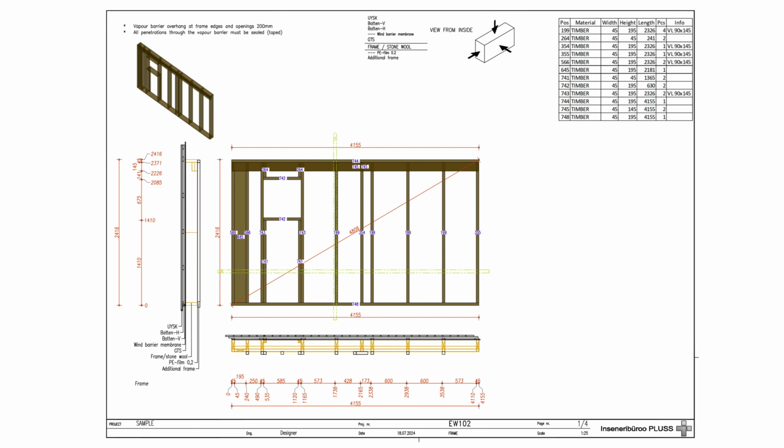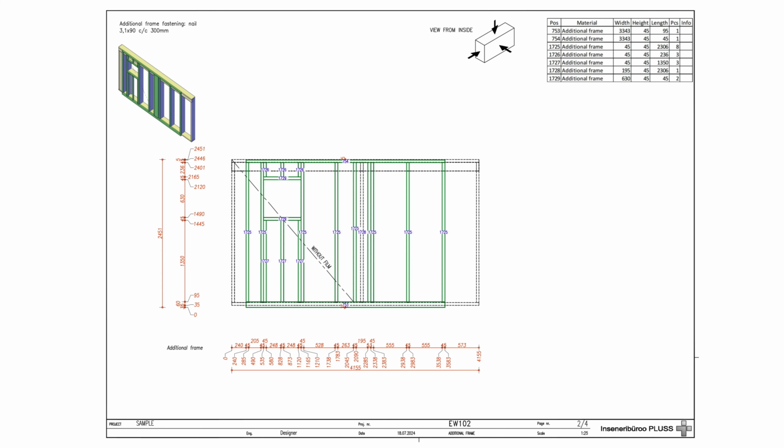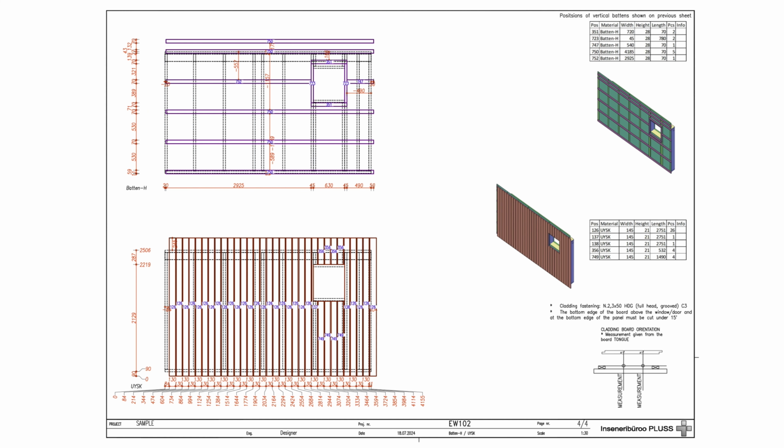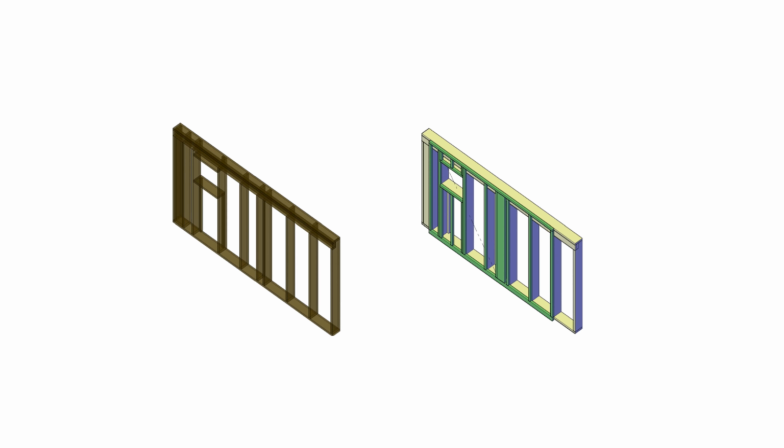In the case of the layout of an element between different drawings, it is important to take into account the technological order in which the element is assembled. In the case of the external wall element, usually the work starts from mounting the room side of the element, which means that on the drawing you see the room side layout of the element.